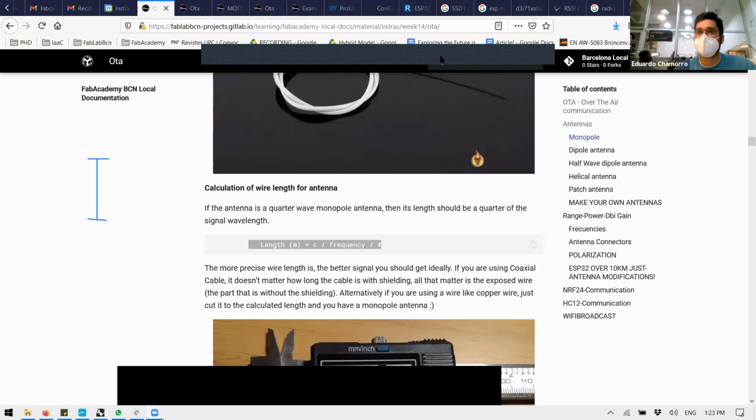No. We use half or 1/4 of the wavelength for the antenna length, because with the 1/4 we almost get the same as the full, but at 1/4 of the size, and with the half we get almost the same as the full length. What happened? We just need smaller components.